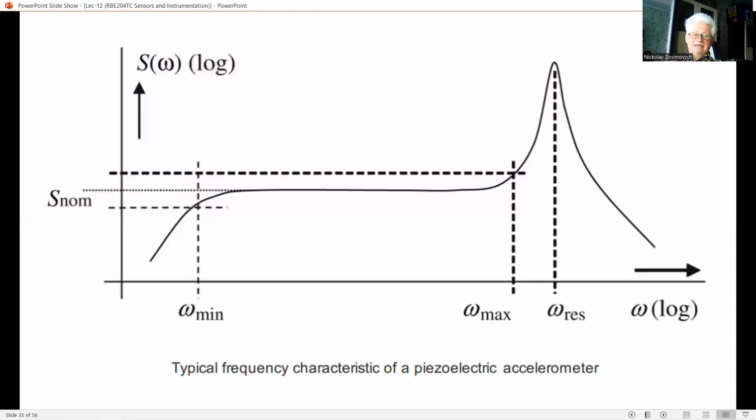The sensor is modeled as a second-order system and shows a frequency characteristic similar to the one given in this figure, with a resonance frequency of 6.1 kHz. In applications where dynamic performance matters, for instance, as active rate of force sensors, PVDF sensors appear to be suitable devices.